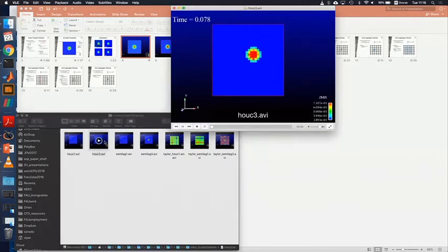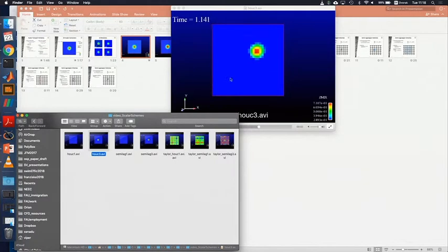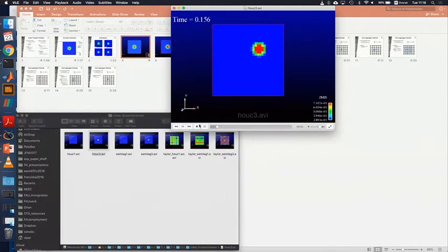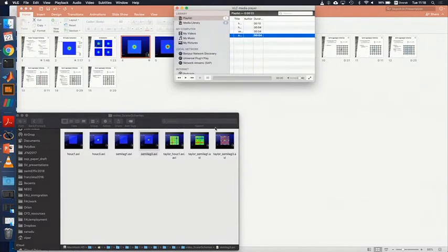If we go to a third order scheme, the diffusion goes slower, but eventually if I run it for long enough, the blob will diffuse out. If I use another scheme called semi-Lagrangian order 1, again, almost immediately it disappears. But if I use a third order, now you'll notice that the blob stays. So this is where the scheme that you pick to discretize becomes very important.